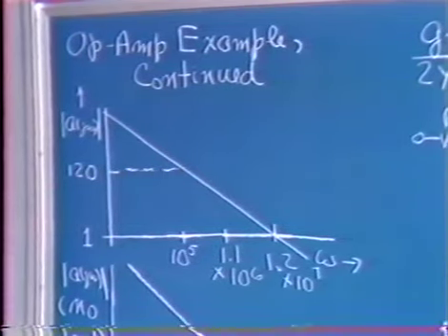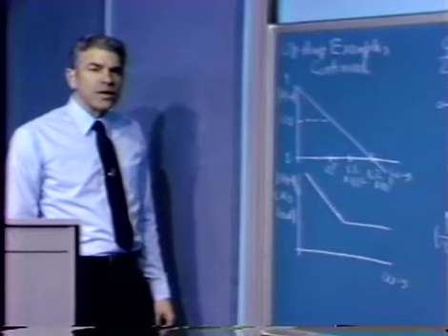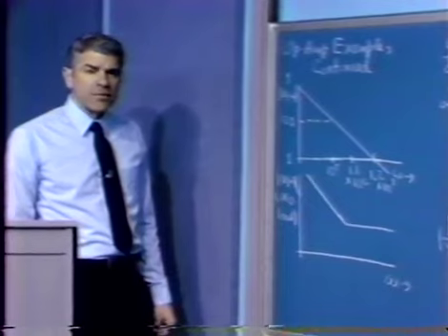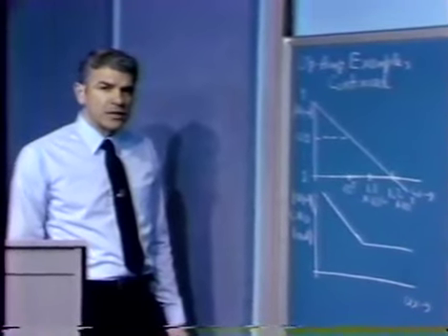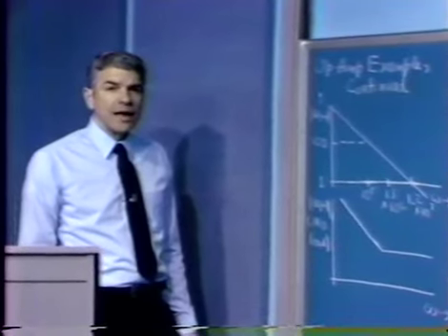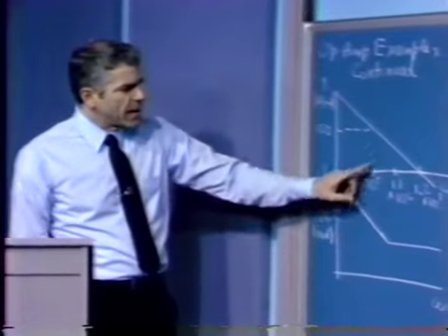The output resistance of the amplifier is somewhere on the order of 100 ohms, and consequently when we load the amplifier with a 1/10 of a microfarad capacitor, we'll put in another pole with a time constant of 10 microseconds. In other words, we'll add a pole at 10 to the 5th radians per second, back about in here.